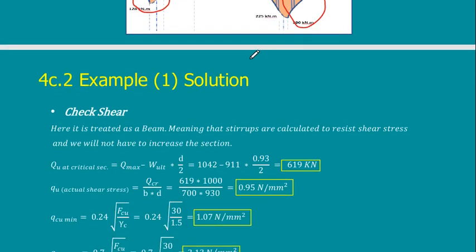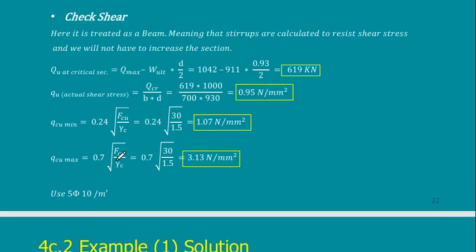Now I need to go to the stage where I design steel and design the depth. But similar to what we said before, check that this footing, according to your dimensions, is safe in shear and safe in punching. If it is safe in shear and safe in punching, then you can design the steel so that you don't have to redesign the steel again.